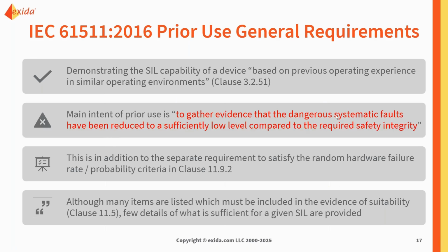If not, we have to follow prior use. The purpose of prior use is, number 1, to demonstrate the SIL capability of a device based on previous operating experience in similar operating profiles. So in other words, are we comparing apples to apples? It doesn't necessarily have to be in a safety application, as long as the operating conditions and environment are the same and the process is the same. But the most important point is that